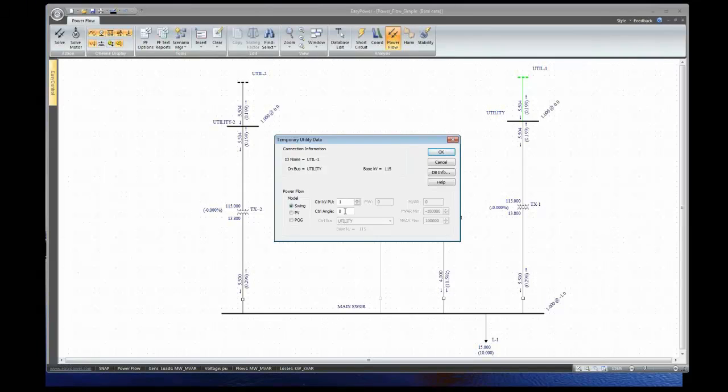In an AC system, when I have a turbine generator and I increase the steam to the turbine, I put more kW into the turbine. The generator tries to speed up, but there's a restraining torque because I'm in synchronism with the system, so it'll accelerate a little, move ahead a little bit, and the angle of the generator to the power system will increase. That's the control angle. And when I have a control angle increase, I'm exporting more power.